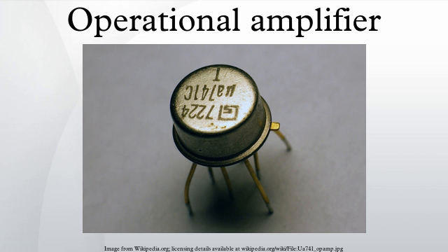The output range of the amplifier is about 1 volt less than the supply voltage, owing in part to VBE of the output transistors Q14 and Q20. The 25 ohm resistor at the Q14 emitter, along with Q17, acts to limit Q14 current to about 25 mA. Otherwise, Q17 conducts no current.